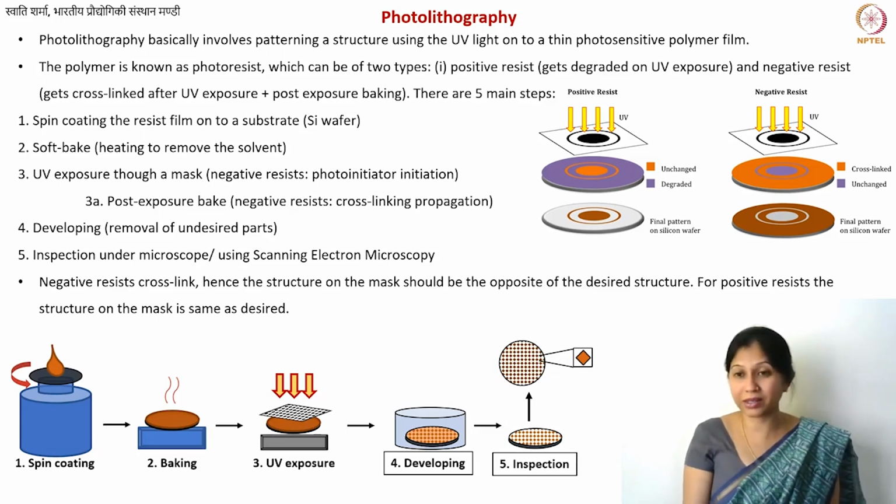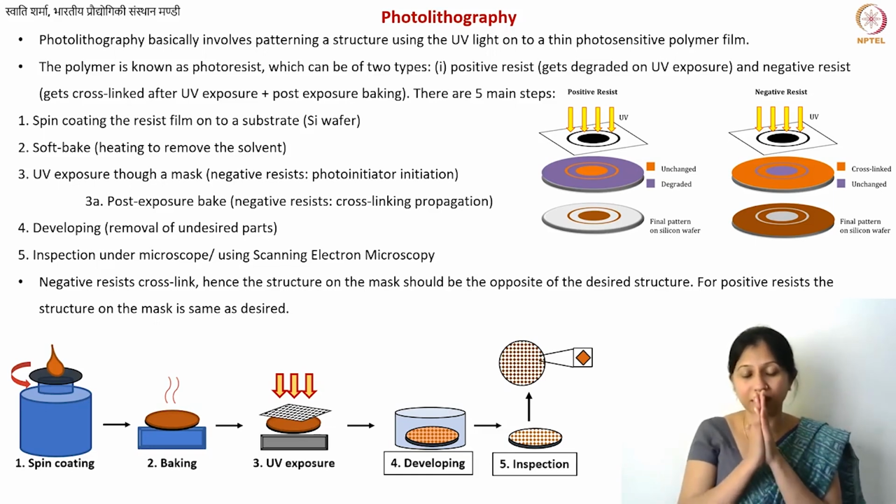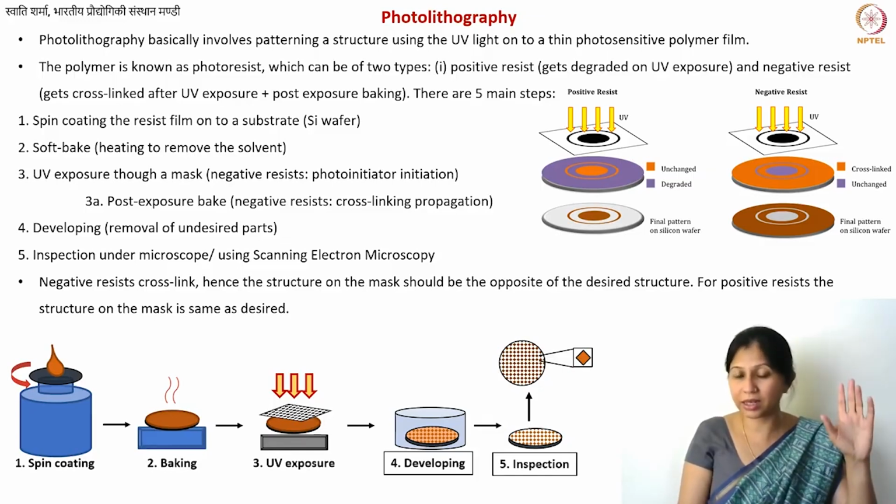We know that if we increase the temperature of the carbon, it will increase the cost of the overall process. That is true, it's energy consuming and so on. But at the same time, you may get higher graphitization. Higher graphitization means higher order. Now this glass-like carbon is a non-graphitizing carbon, so it will never convert into polycrystalline graphite.